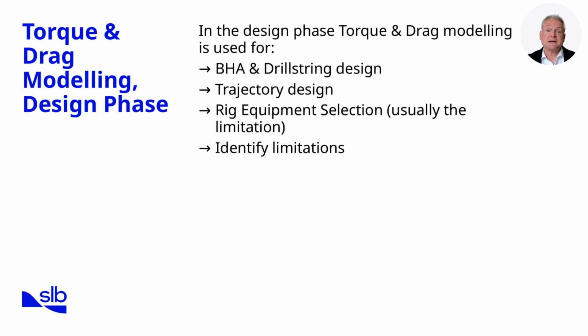In the design phase, torque and drag modeling is essential for planning both the drill string and bottom hole assembly. By simulating forces along the planned trajectory, we can test whether the proposed BHA configuration will deliver the required weight transfer and bit control without exceeding mechanical limits. Trajectory design is another critical aspect.